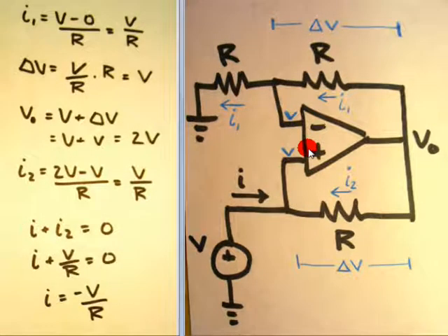Because of the op-amp, the voltage at both the inverting and non-inverting inputs is V. You can solve for I1 to find the current, which then lets you find the voltage drop across this resistor and find V0. Once you know V0, you can find I2. Since current flows from high to low voltage, the current is drawn and flowing to the left.